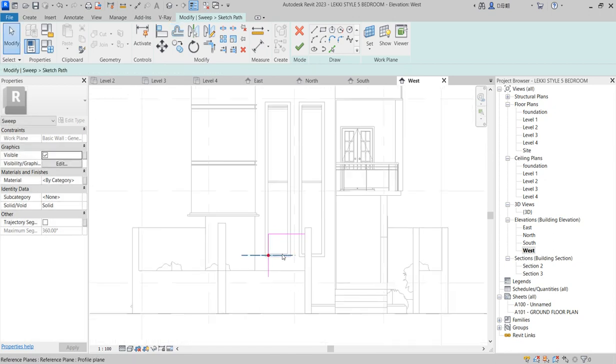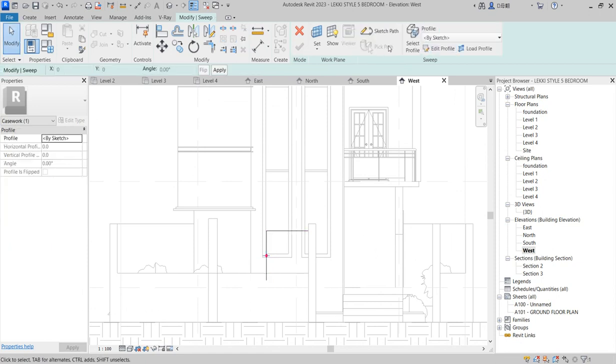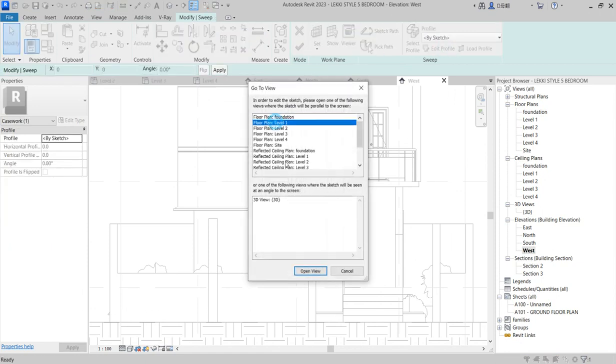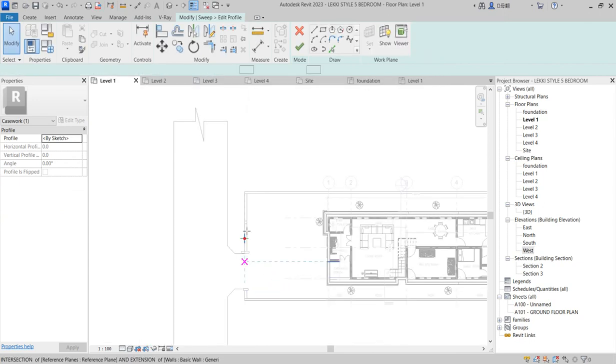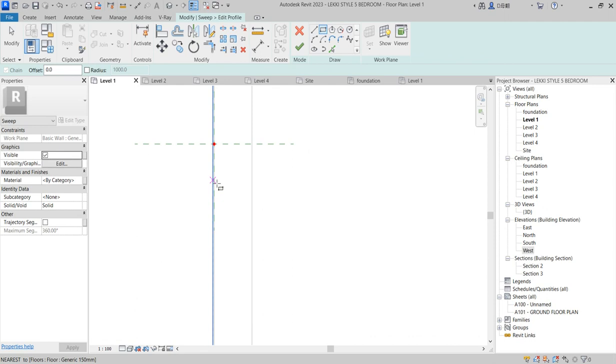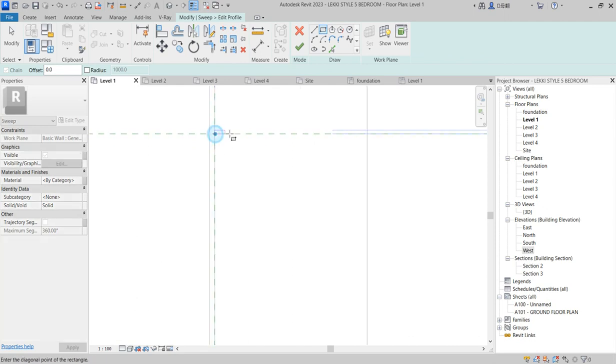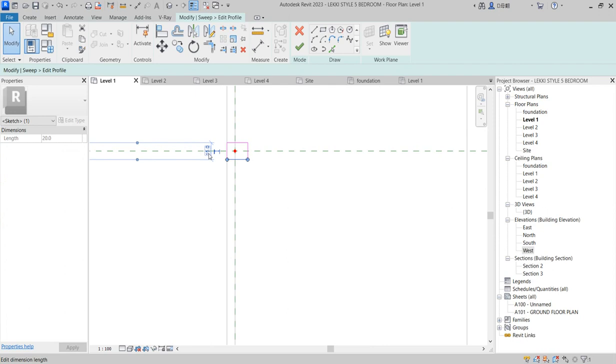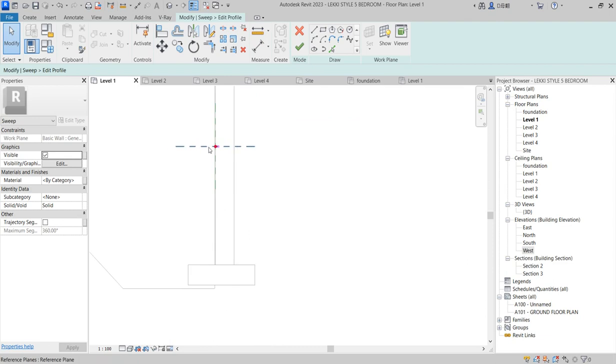As I've done with this one, I need to click finish. Then I will do edit profile level 4, and this is what I need to create now. At this junction, what I just need is the rectangle parts. So I'm going to create this now from the middle or something around it. So select, 15, good. Then 15 by 20 is not okay. Let's say 15 by 50. That is what I need at the junction.